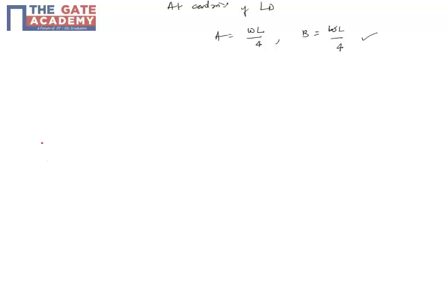Like if you remember the case when you have a simply supported beam with a UDL, which is again symmetric in loading. Where did you expect the maximum bending in the bending moment diagram? The bending moment diagram for this case was a parabola peaking at the center. So in this symmetric case, with a constant UDL acting, you got the maximum at the center. This is how the bending moment diagram looks for this case.